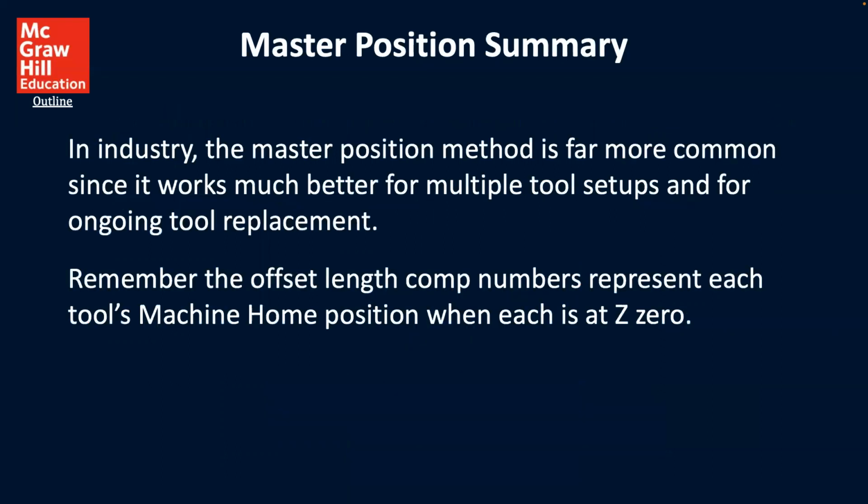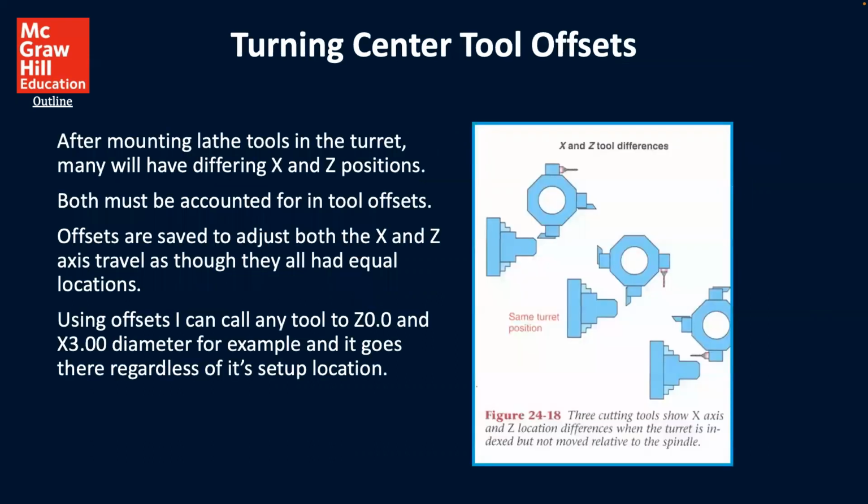So the master position summary: in industry, the master position method is far more common since it works much better for multiple tool setups and for ongoing tool replacement. Remember, the offset length comp numbers represent each tool's master home position when each is at Z0.